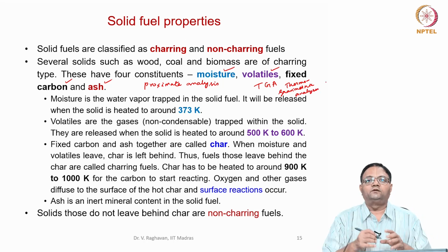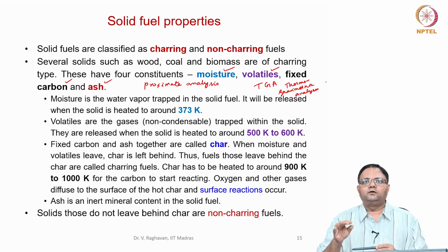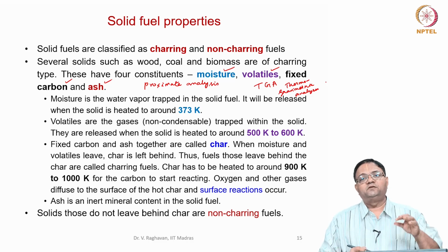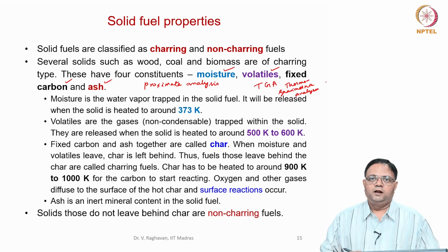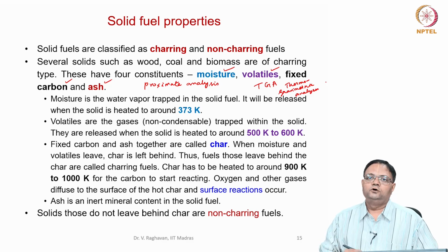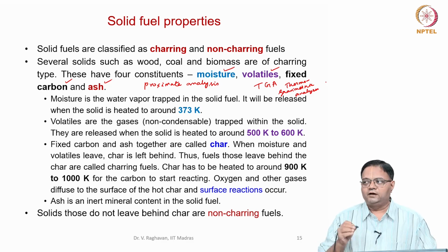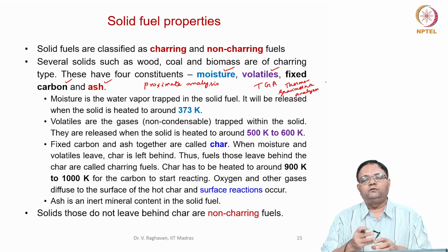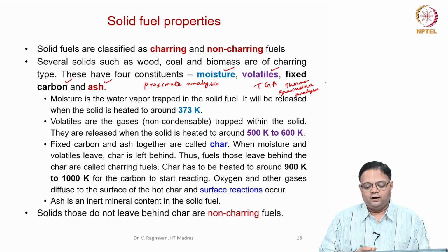So I put the solid sample in this. I can use any agent, nitrogen or oxygen or air. But what I have to do is send hot gases through this, and there is a specific heating rate which I can set, like say 30 degrees per minute, 40 degrees per minute, etc.